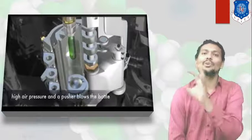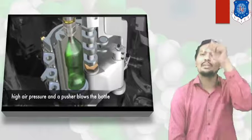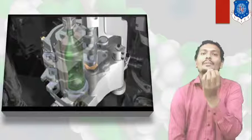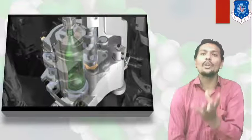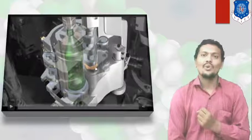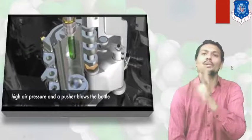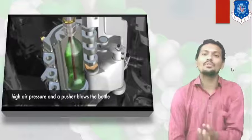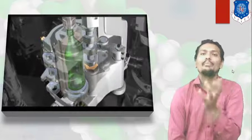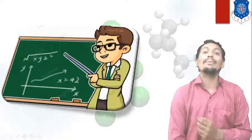Here between two dies, one plastic component is placed, and with the help of blowing air with some rod, you can blow your bottle, or in simple words you can make your bottle, right? Once again, let's have a look at the blow molding. Between two molds, with the help of some blowing rod, you can make your bottle with the help of air pressure, right? This is known as the blow molding process, right?